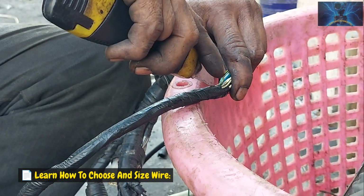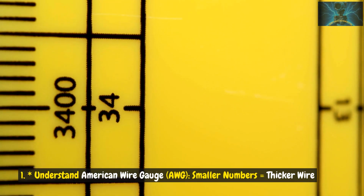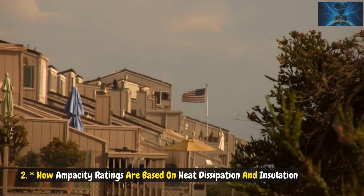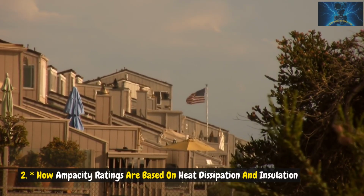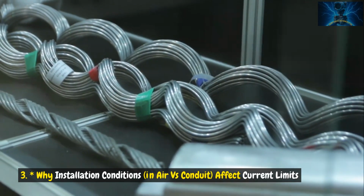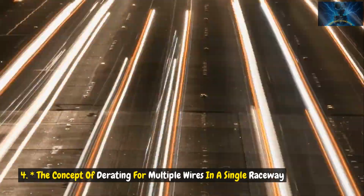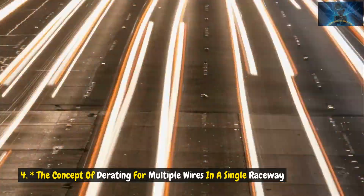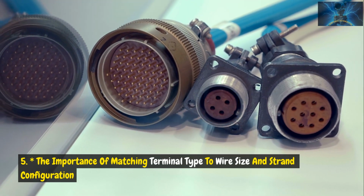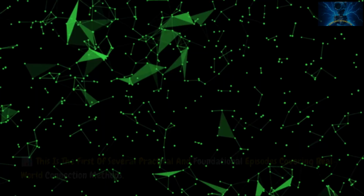Learn how to choose and size wire. 1. Understand American wire gauge, AWG. Smaller numbers equal thicker wire. 2. How ampacity ratings are based on heat dissipation and insulation. 3. Why installation conditions, in air versus conduit, affect current limits. 4. The concept of derating for multiple wires in a single raceway. 5. The importance of matching terminal type to wire size and strand configuration.